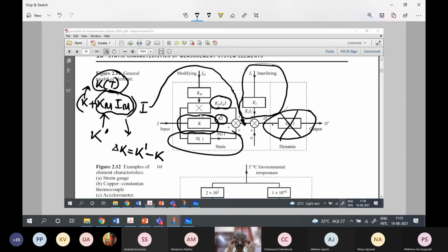But obviously it will be an approximation. Nothing is linear if you split hair. So the question is, for the purpose of your measurement, the application, the kind of accuracy you need, is it okay to look at it as linear? In more than 90% of cases of measurements, it'll be good enough to say that it's linear. There'll be a slight error. So sometimes what we try to do is hide the nonlinearity into an error description when it is small enough, just to make this instrument look simple.